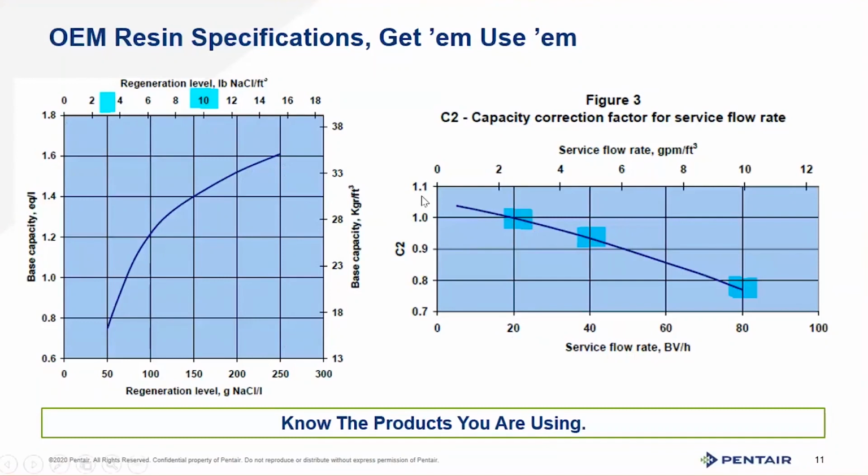But if we extend this line out down to here at 70%, up to 11 GPM approximately, now we understand where that 30% reserve capacity comes in. It helps us prevent overrunning the softener with flow rate. But if we design our system properly for the customer, we can stay up in here without having to adjust. One simple graph gives us a lot of reasoning for why decisions were made in the industry.